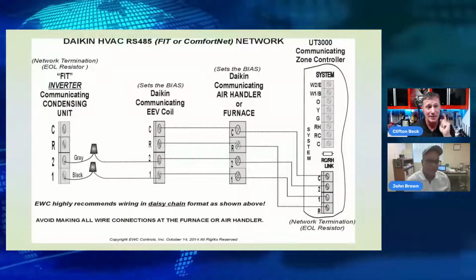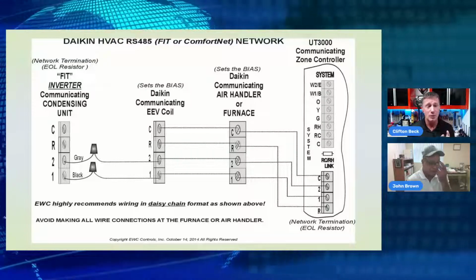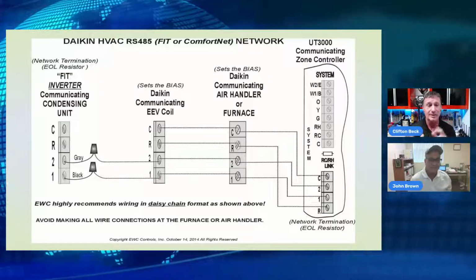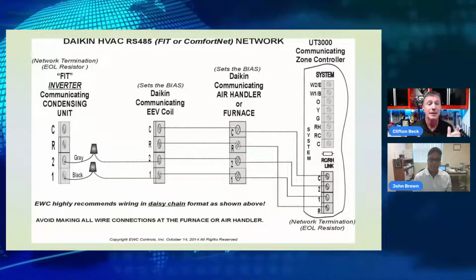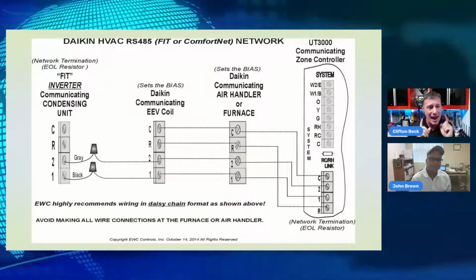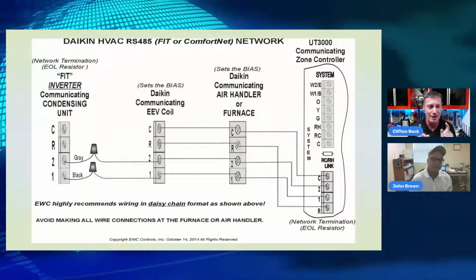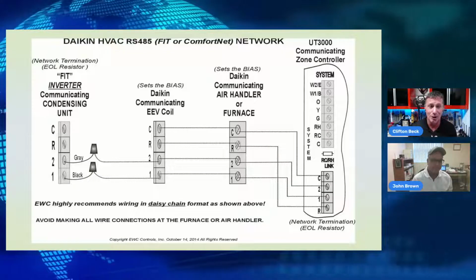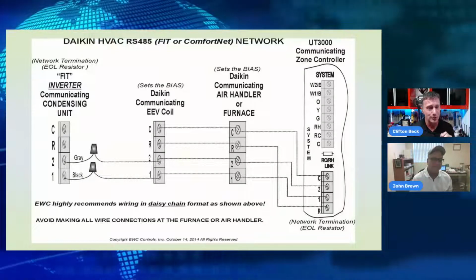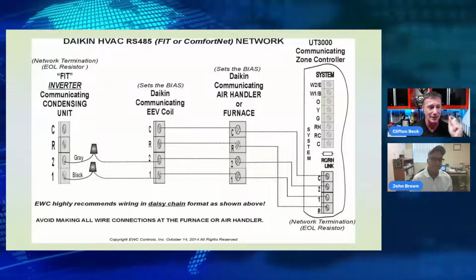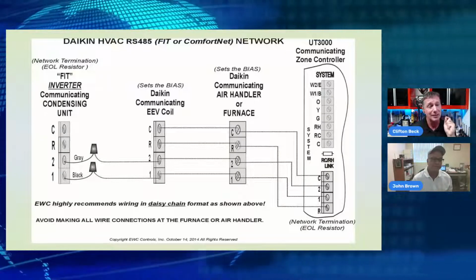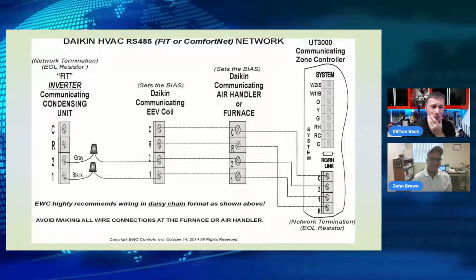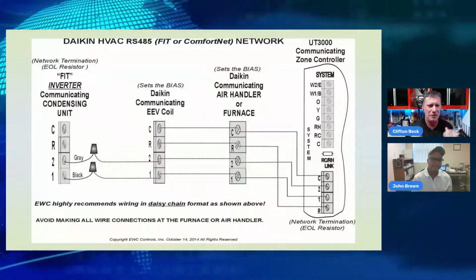And that's the thing to point out about that electronic expansion valve, that not everyone realizes that we are moving to electronic expansion valves to replace standard thermostatic expansion valves. But they are absolutely an asset to us if we understand how they function. If we take this electronic expansion valve, I know this particular one has two temperature thermistors, one on the inlet of the evaporator, one on the outlet, and now we can start using a pressure transducer, a suction pressure transducer. And technicians go, oh my gosh, all that technology.